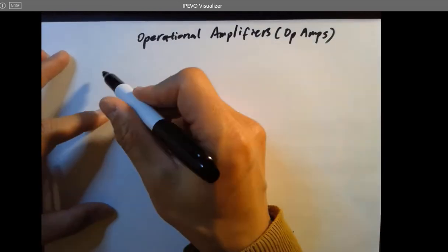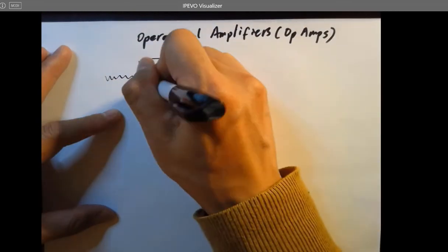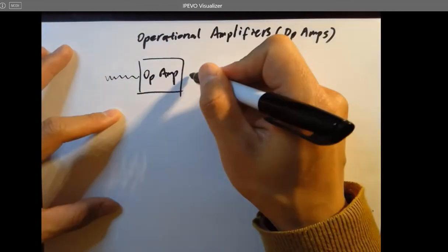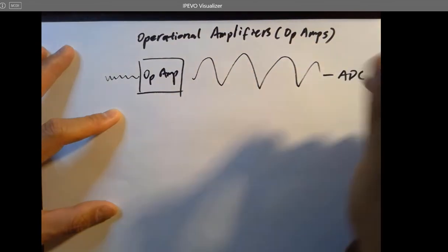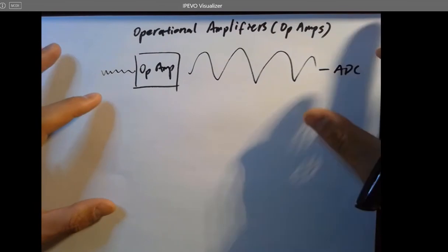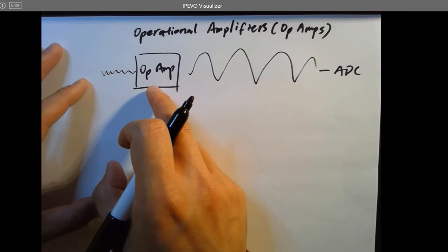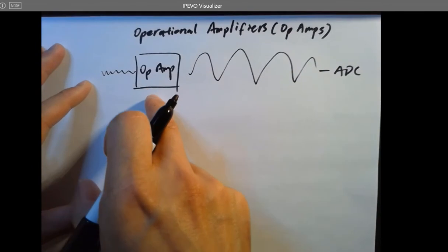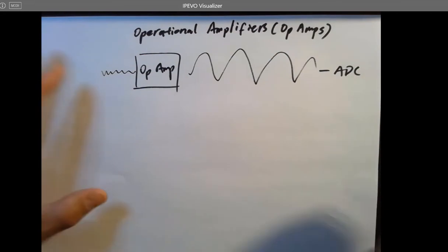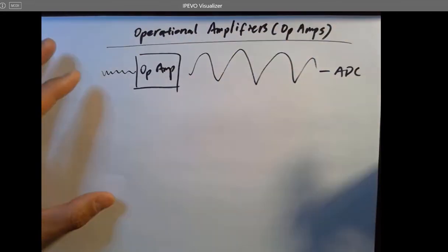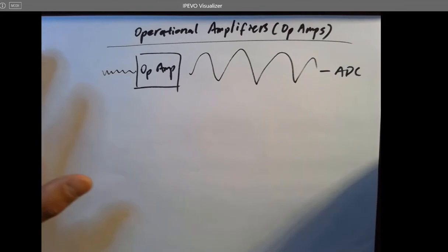If you have a small signal and it runs through an op-amp, it is supposed to be amplified. So your ADC is able to detect it and then it is sent to a computer so you can store the data somewhere. Okay. So this is being used as a front-end amplification tool in pretty much all these data acquisition platforms and sensors, electronic circuits, all these kinds of things.